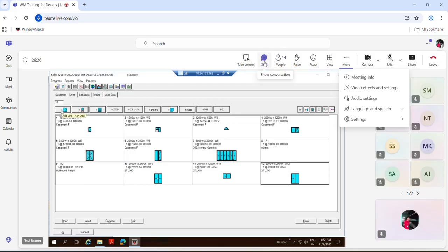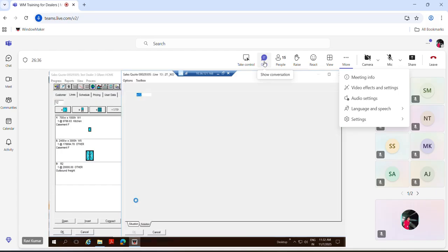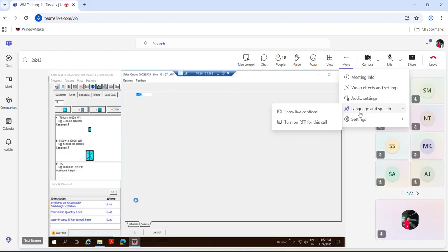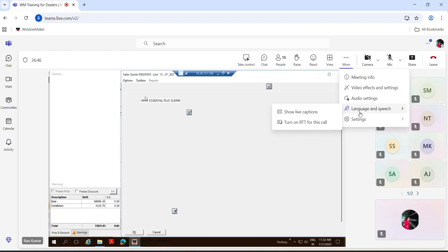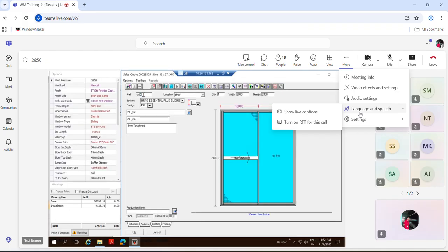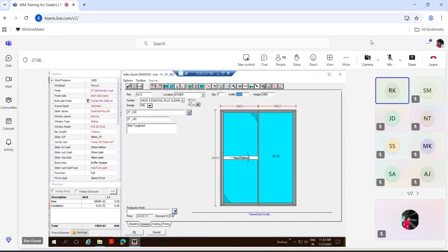So our next series is ETSD Pro. So ETSD Pro maximum panel width you can consider 1200 mm for slider part, and for fixed part you can increase to 1500 mm.